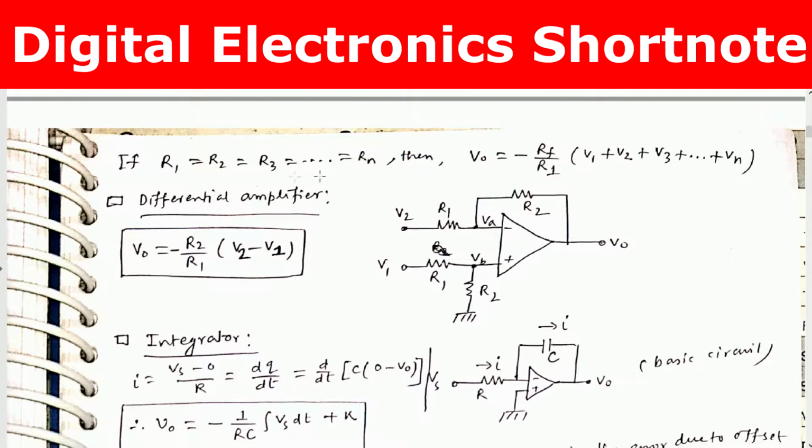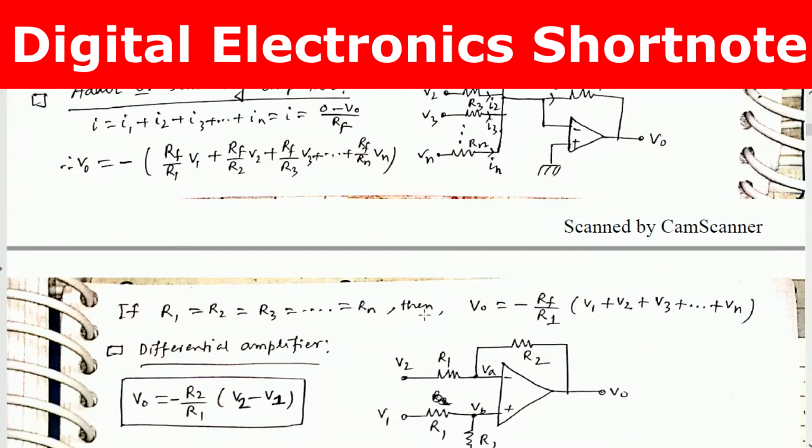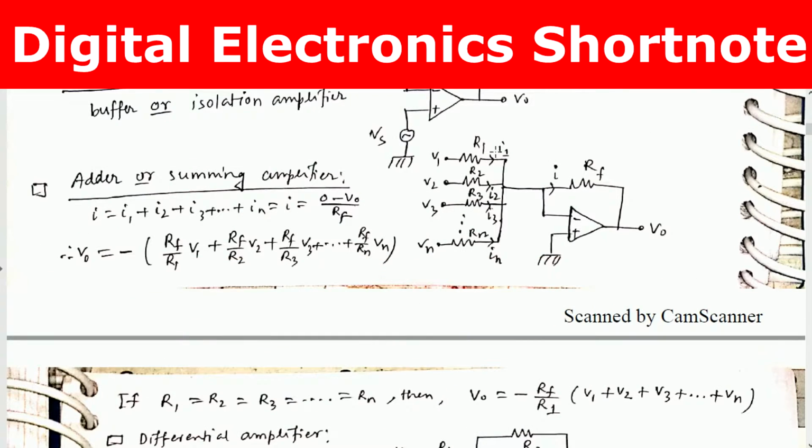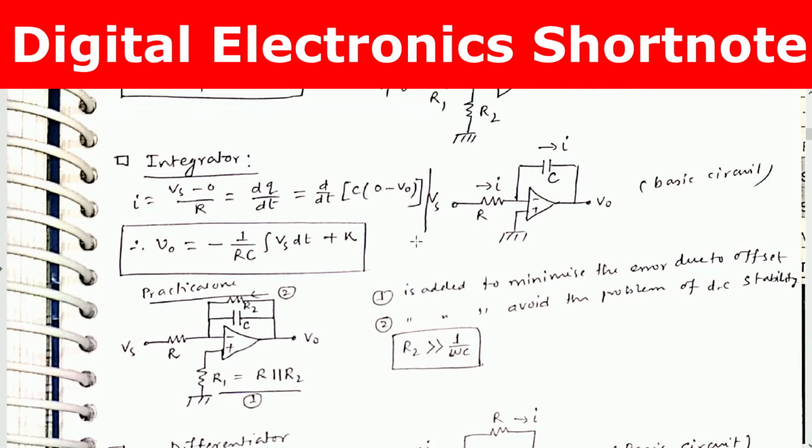If R1 equals R2 equals R3, that is, if these resistances are all equal, then V0 is written as minus Rf by R1 into V1 plus V2 plus V3 and so on up to Vn, where the resistances have equal value R1. This is a differential amplifier, which amplifies the difference of the provided signals. So this is the formula: V0 equals minus R2 by R1 into V2 minus V1.